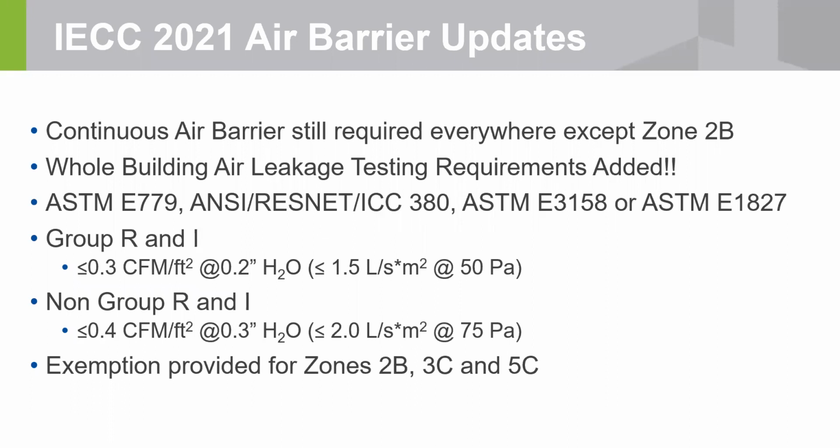So, when they list that air barrier, what does it have to be? Well, it says either tested or comply with the things that it lists. It has to be continuous. The seams and transitions and penetrations, et cetera, have to be sealed. It talks about fenestration air leakage, rooms containing fuel burning appliances, doors to shafts, elevators. Well, all of that would still apply, but evidently that stuff goes out of the way because it tells you, well, if you test it, you can test it, and then only the air intake exhaust, loading dock seals, vestibules.